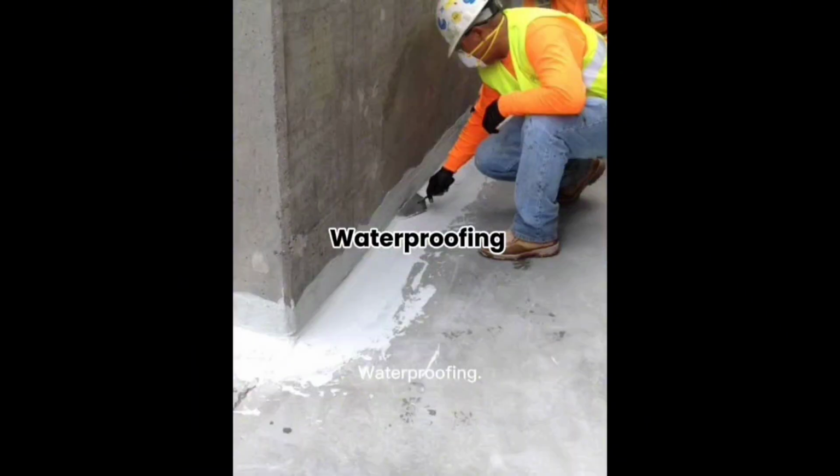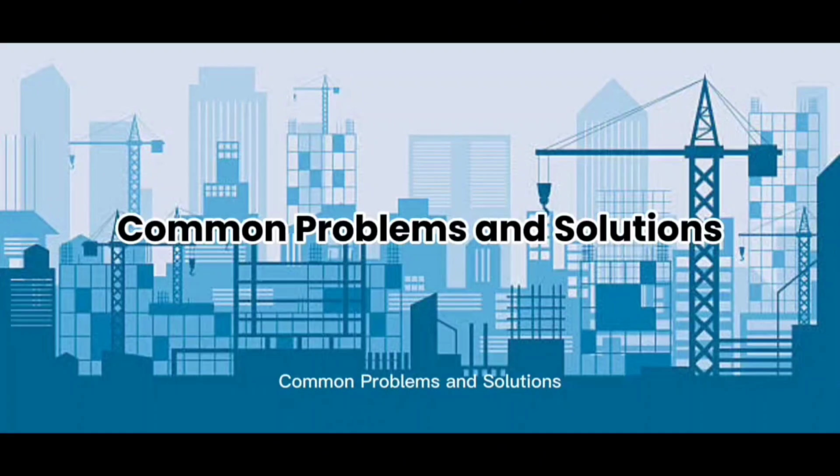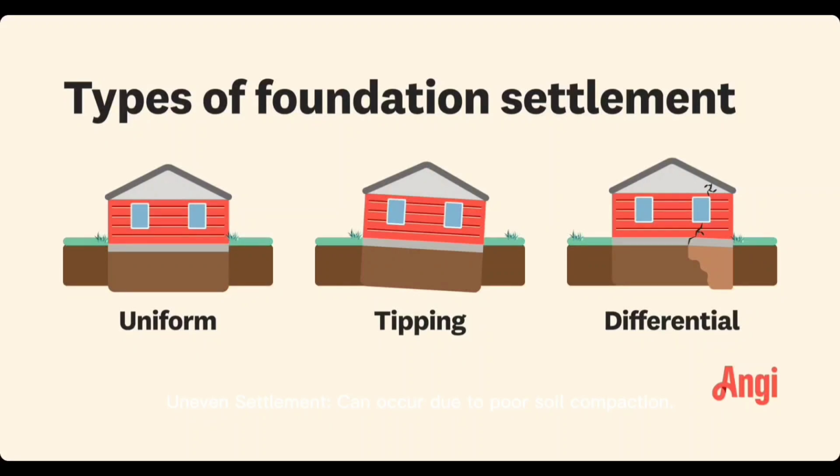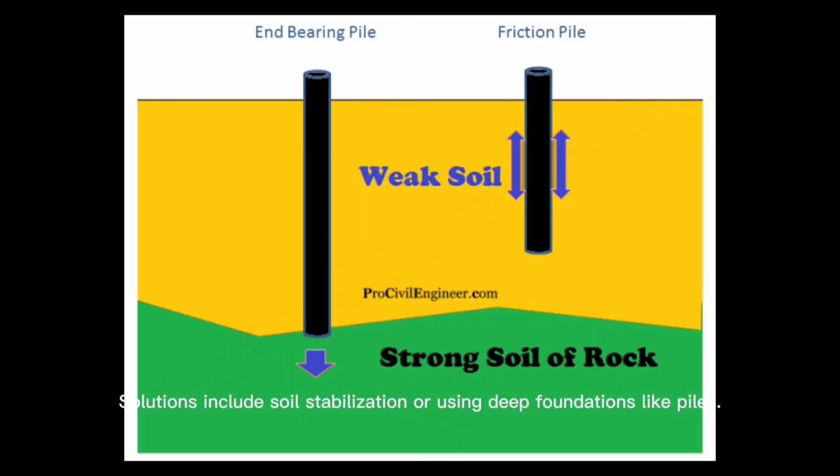Waterproofing. Foundations may need to be waterproofed, especially in areas prone to moisture or flooding. Common problems and solutions. Uneven settlement can occur due to poor soil compaction. Solutions include soil stabilization or using deep foundations like piles.